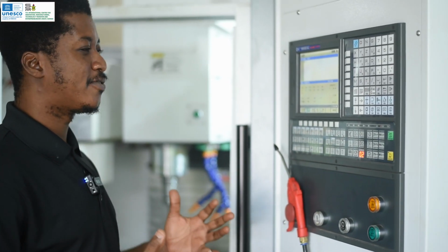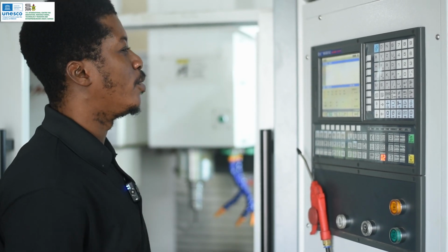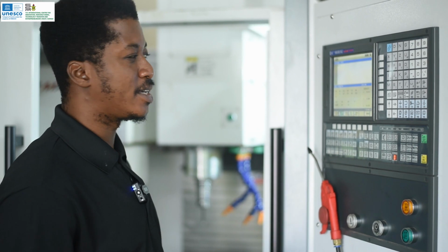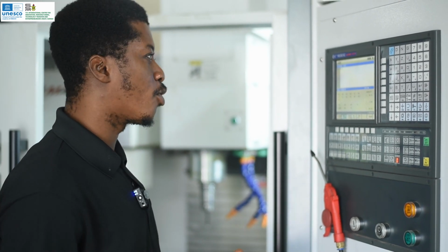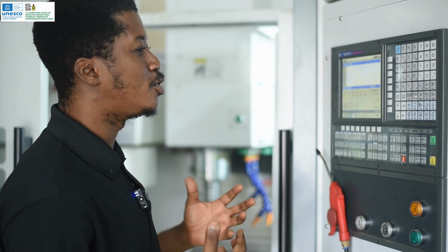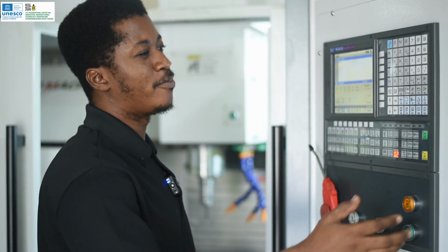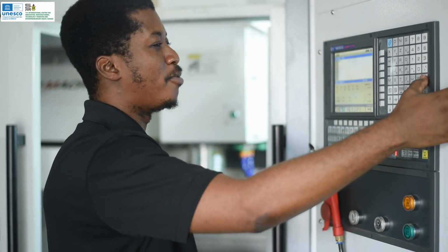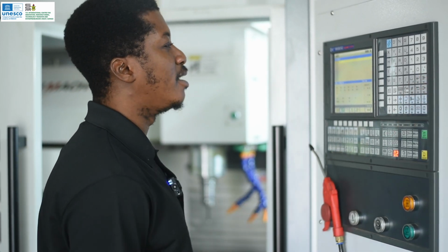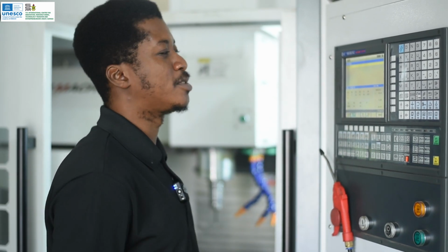So we want to change from tool 2 to tool 5. We have entered the command M6 followed by the T4 command, so we're going to be changing that. To be able to do that, right after entering your command, you would press the data input button, and this puts us in the mode that allows us to execute this particular command.